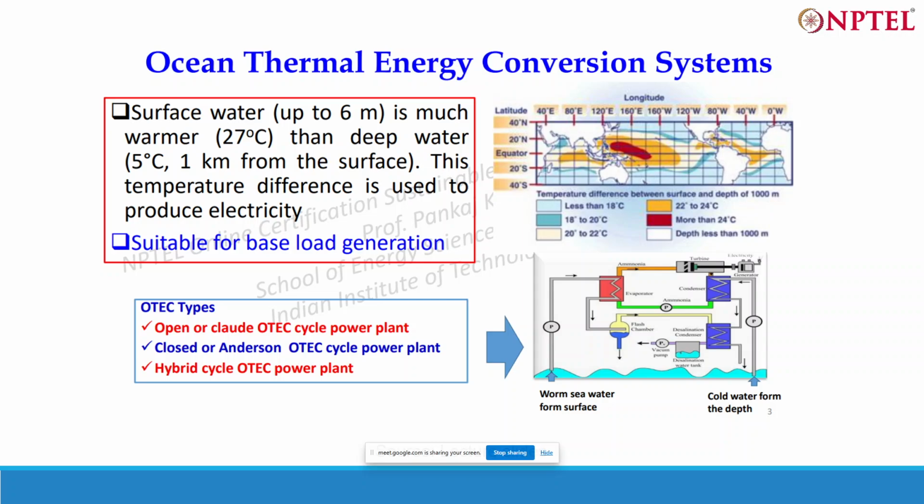So there is a temperature difference, a thermal gradient, that can be utilized to run an organic Rankine cycle. This cycle runs on a refrigerant instead of the steam we use in a common power plant. Using this, we can have a small power plant that provides power to a generator and then electricity to the nearby areas.